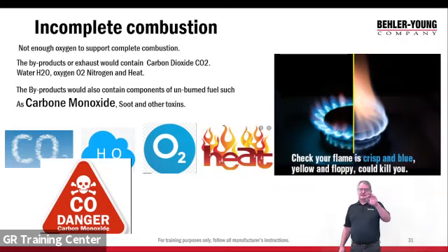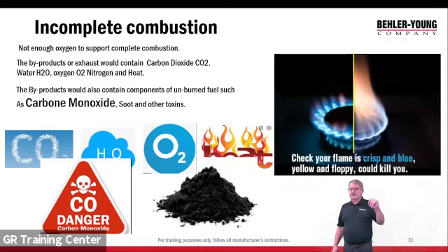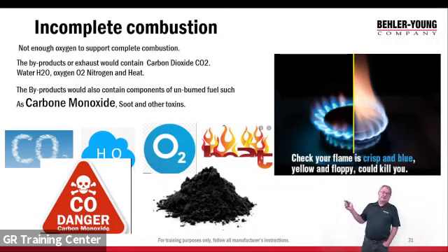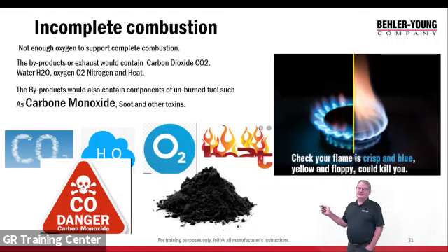If there's any of you newbies out there who've been on a furnace that's sooted, you're going, oh, I could smell it. No, you couldn't. There are some other gases along with the carbon monoxide that you're going to smell. Then there's carbon itself, this black sooty stuff. Imagine powdered sugar that's black. Throw it up in the air. That's what the soot looks like off of a furnace that has not been burning properly. And it's just as messy as what I described to try to clean up.